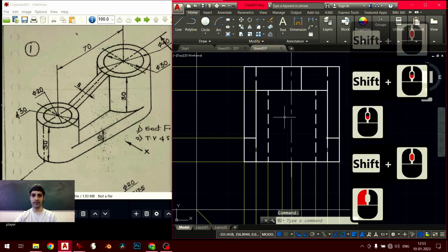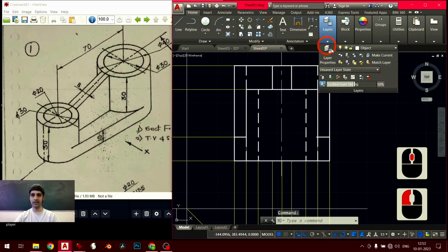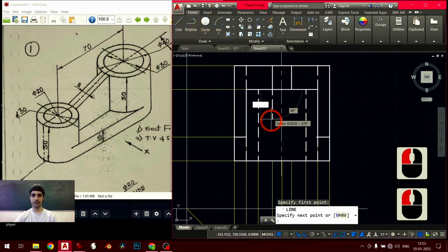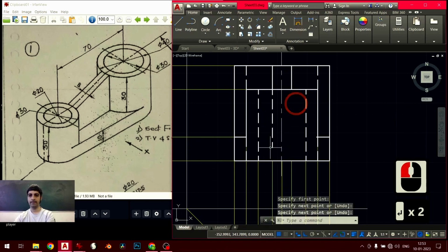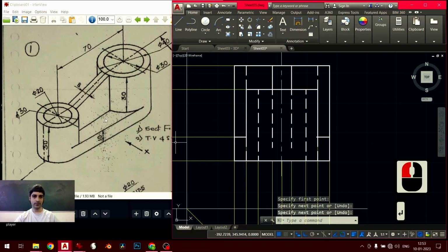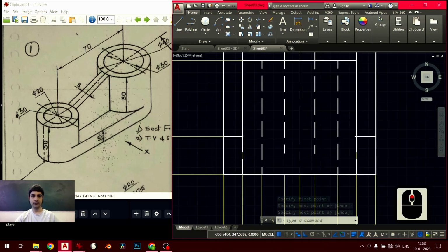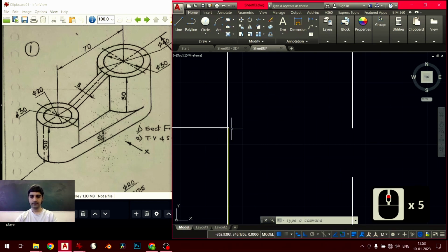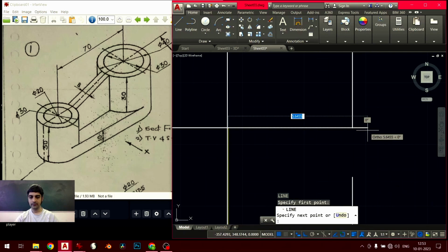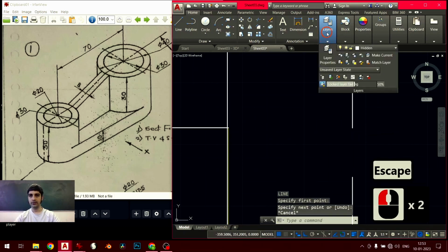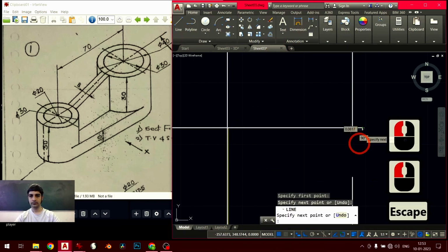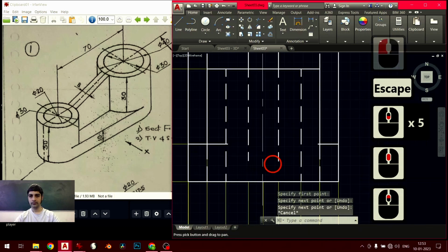So we'll take care of that here, for which I'll extend a hidden line from this point all the way to the bottom, and then here as well. Along the same lines, this curved edge that's formed, some of it is hidden behind the cylinder in front. So after this point, on both sides, you'll be stretching out a dashed line on the hidden layer, and on the other side as well.